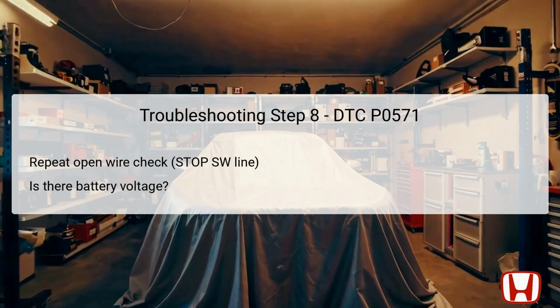However, if voltage is missing, it points out that there is likely an open in the wiring, necessitating further investigation and repair. Properly following this protocol ensures that technicians can accurately diagnose any remaining issues related to the DTC.